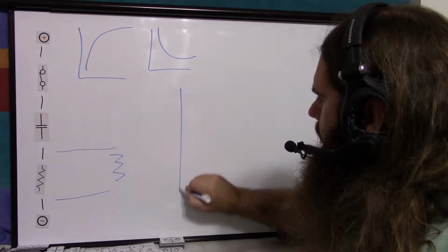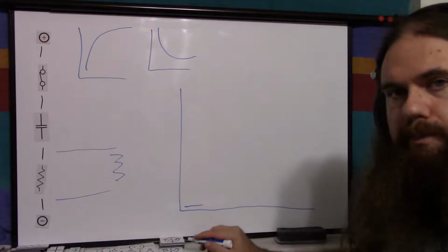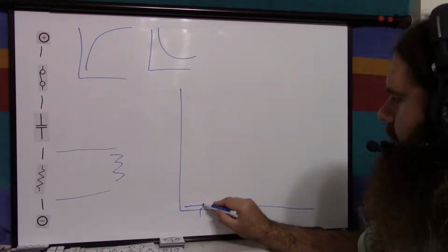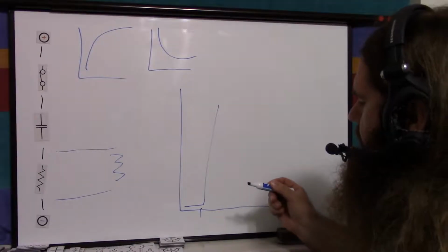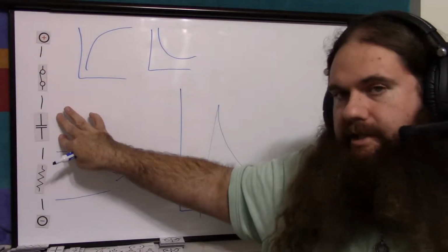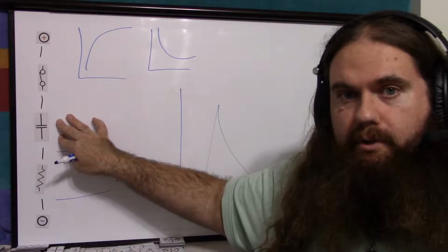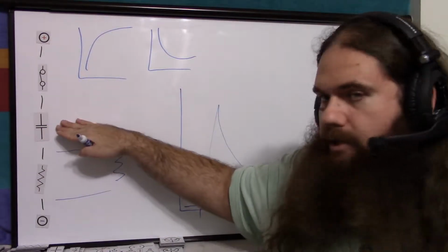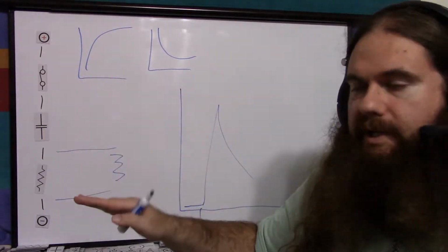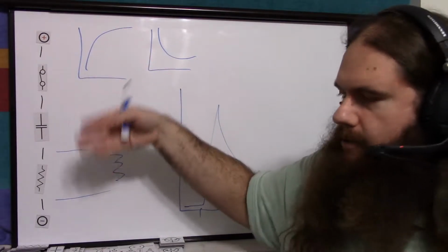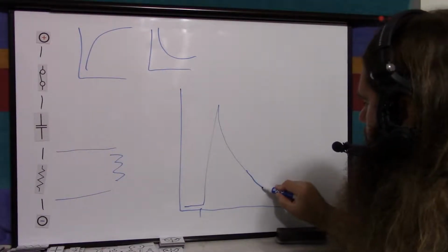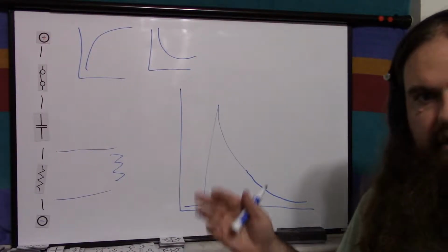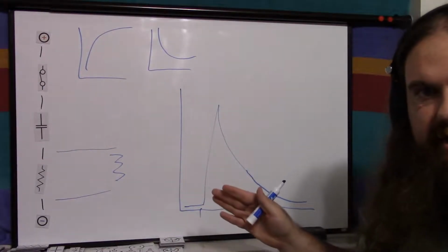So if we begin our graph at the beginning at 0, then we close the switch there, and the voltage jumps up because all of a sudden this thing is charging as fast as it can. But then drops back down because this thing is charging, which means it's starting to oppose the current, right? Because a fully charged capacitor in a series arrangement like this is going to stop the DC. It'll effectively pass AC, but DC it'll block. So it eventually tapers down to 0. And of course, your tau time constant is involved here as well.